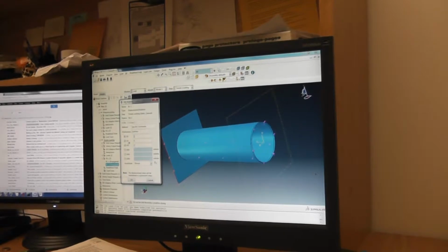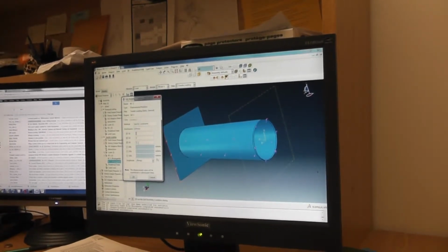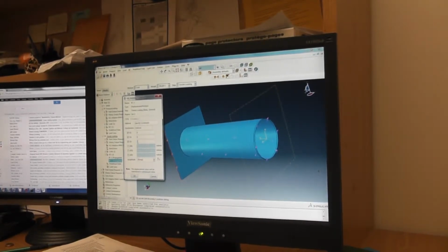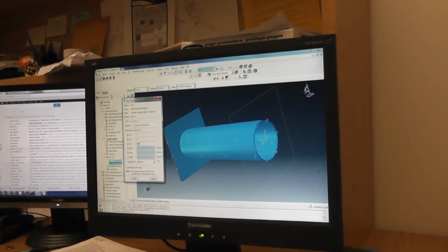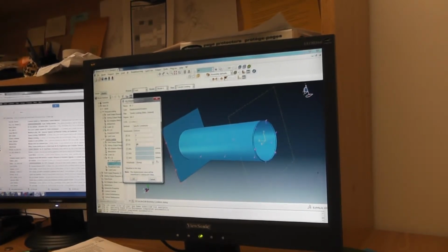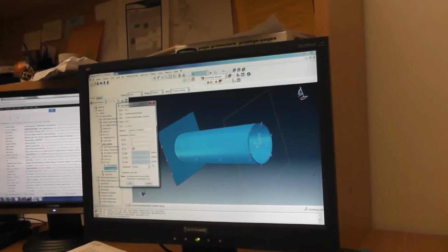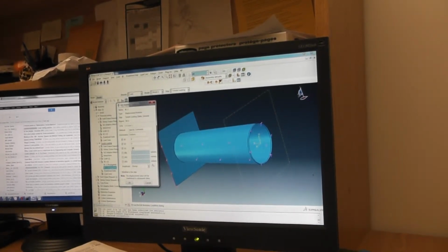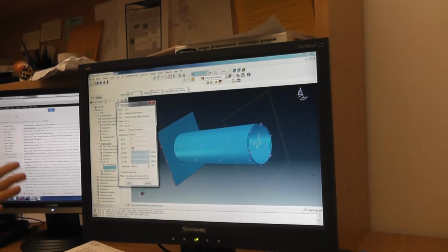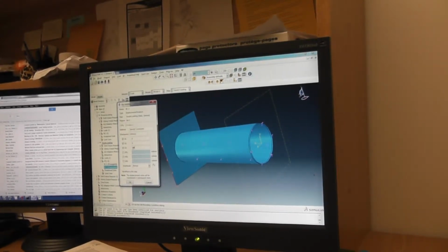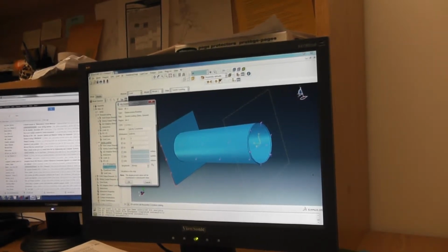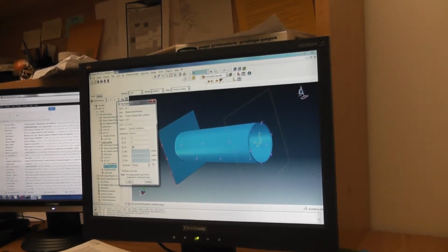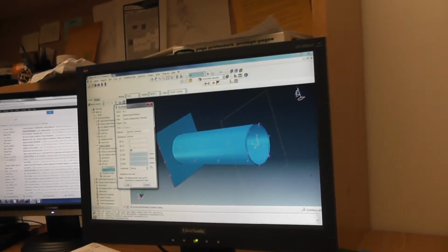So let's just fix U1, U2 and move it in U3 a distance of let's say 300 millimeters. Let's apply. So what's that remote strain? We have this, the distance is a meter. So this is 30% strain. We're applying 300 millimeter, so that's 30% strain.